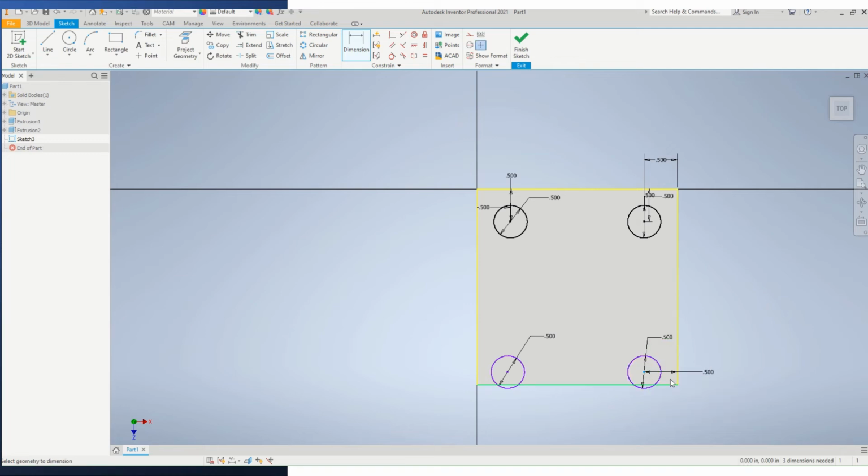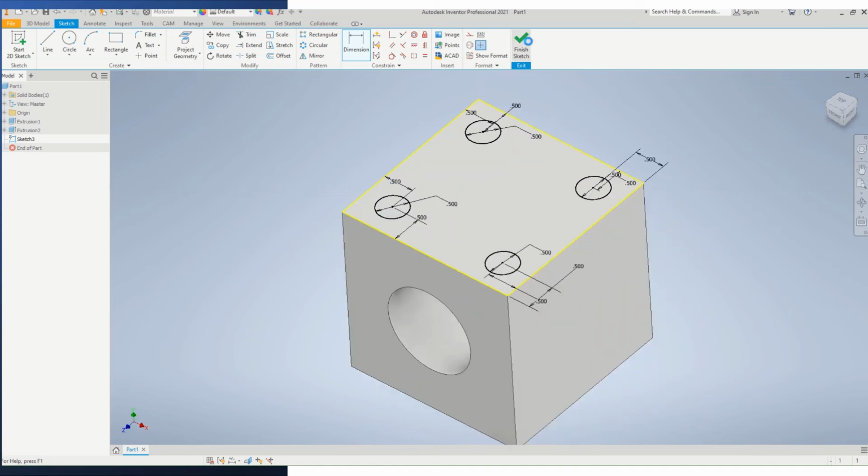Same thing here, we're almost done. So this is if you're adding some bolts to an object, if you need holes to go all the way through with some type of pattern so that something will seat inside of an object. But right now we have 1/2 inch circles that are a 1/2 inch from each of the edges. So if we want to cut these or add something to this, we would go finish sketch.